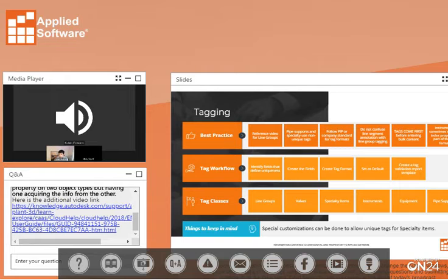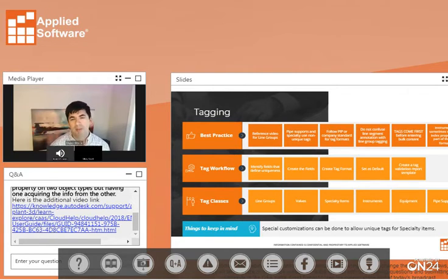Also, do not confuse line segment annotation with line group tagging. As a newbie to tagging, this is something that always confuses people. They say, wait, but I did put it in the line segment, or excuse me, the line. And then they realize, oh, no, that's the line segment, not the line group. It happens all the time. It's just something you have to watch out for. It also happens on the 3D side. People expect to be able to tag the size, the service, and the spec when they start routing pipe. It's inappropriate to do it there because you can create a lot of extra duplicates for yourself. Exactly.